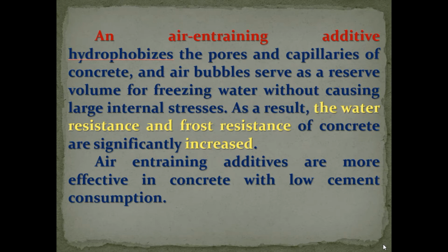An air entraining additive hydrophobizes the pores and capillaries of the concrete, and air bubbles serve as a reserve volume for freezing water without causing large internal stresses. As a result, the water resistance and frost resistance of concrete are significantly increased. Air entraining additives are more effective in concrete with low cement consumption.